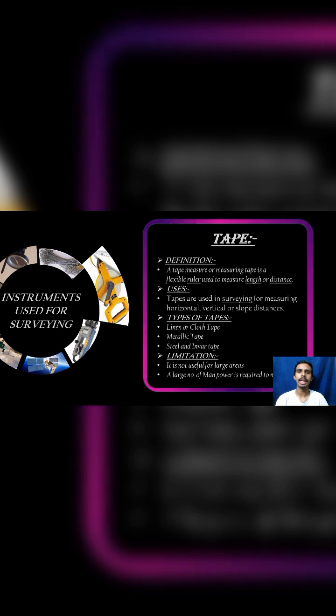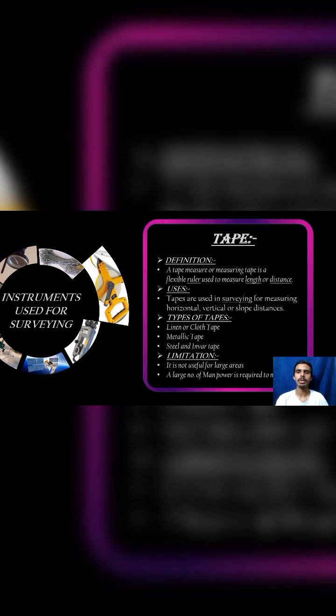So the next instrument that we're going to be looking into is tape. A tape measure or a measuring tape is a flexible ruler used to measure length or distance. Tapes are used for surveying horizontal and vertical or slope distances. The types of tapes are linen or cloth tape, metallic tape, steel tape. Limitations: it is not useful for large areas, and a large number of manpower is used to measure lands using this instrument.